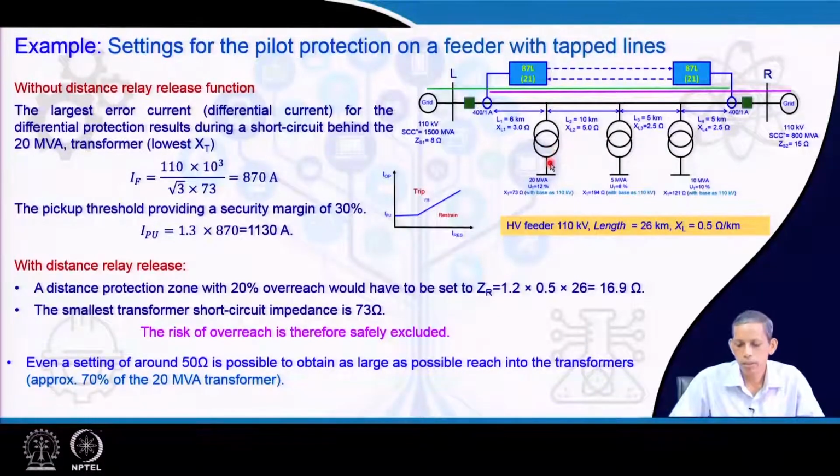The largest capacity transformer will have a smaller impedance relative to the other transformers, and if we create a 3-phase fault beyond the transformer, the corresponding fault current will be more significant beyond the transformers in the tap lines. Therefore, we consider the highest transformer capacity.